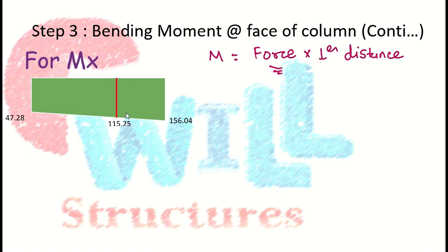No, why? Because whatever values you have determined for the upward pressure, okay, those values' units are kilonewton per meter square. So they are nothing but the stress, right? Because that is P by A, correct? And you have to determine here the forces, and we know that the unit of the force will be kilonewton, correct? So how to determine the force? With the help of these particular values, we just have to determine the area of this section, right? And we can determine the force.